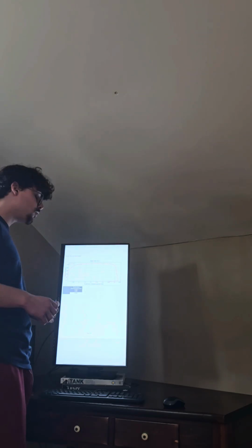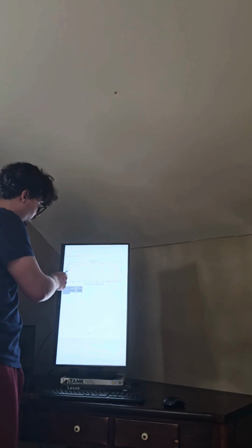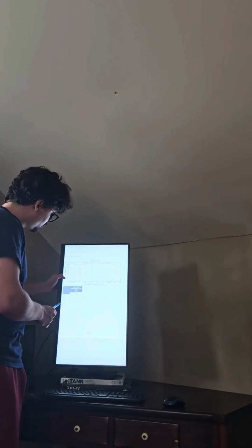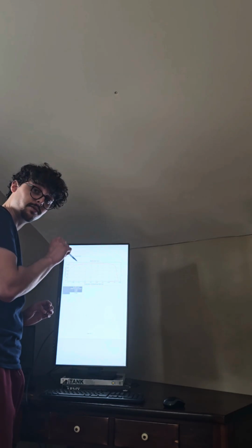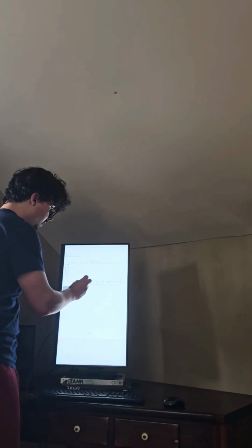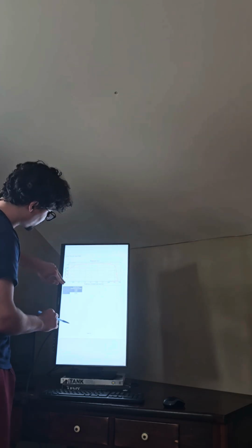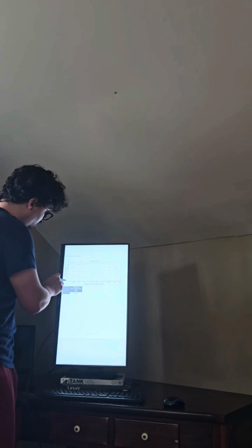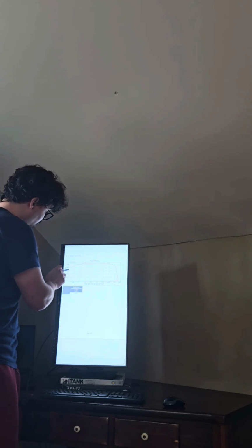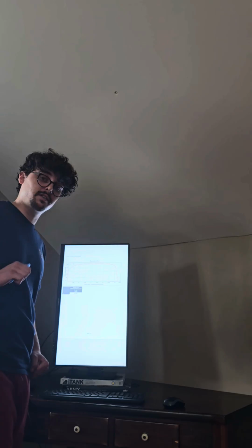Now, how do we get our yield strength? Well, we already have our yield point. So now what we will do is an offset of 0.002 of strain. So it will be something very small like this. And then we will do a parallel line with the elastic region, and whatever this other line that we did intersects, that will be our yield strength.